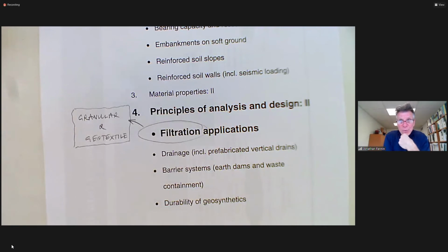And then when we get into waste containment facilities and mine waste sites, we get into relatively large magnitude, but relatively lower frequency. A lot of the learning that we end up doing about geotextile filter design tends to be driven by the bigger projects with the bigger budgets, where the risks or consequences of failure are unacceptable and may lead to loss of life and or enormous costs to rehabilitate the failure.